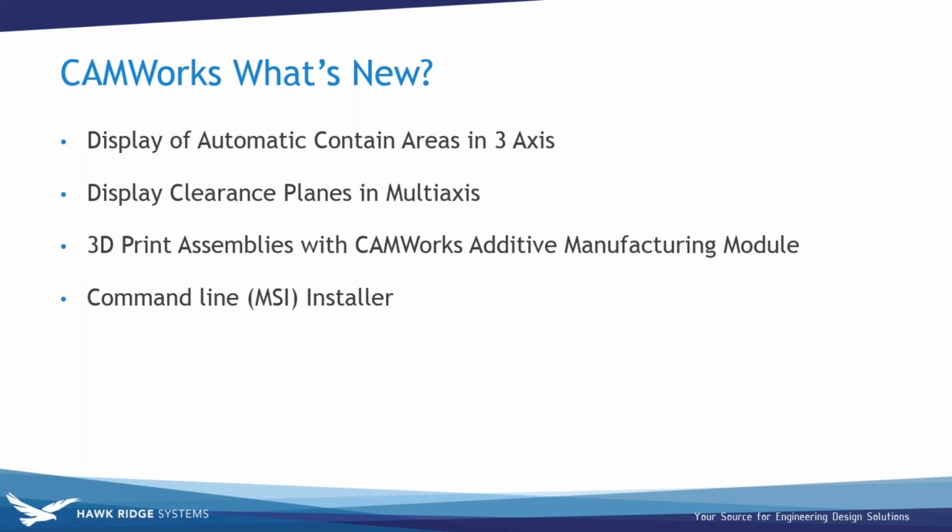So rather than programming CNC mills and lathes, you're essentially programming 3D printed files in a standalone package in one interface. Then you use what they call a build processor, essentially the equivalent of a post processor in the CNC world, and that basically translates the code to a particular printer. Now they actually have support for doing assemblies. So if you want to stack a gazillion parts on your print bed, lay them all out and optimize that, you can certainly do that now in additive manufacturing.